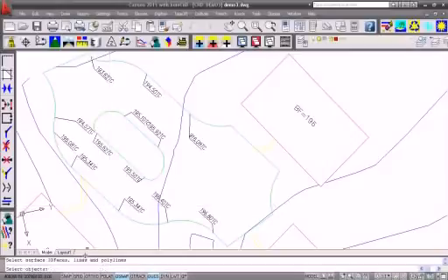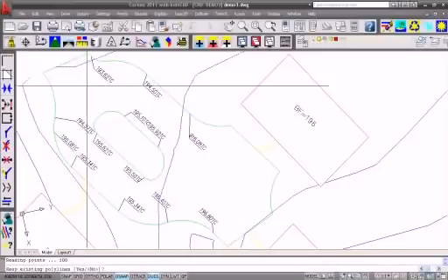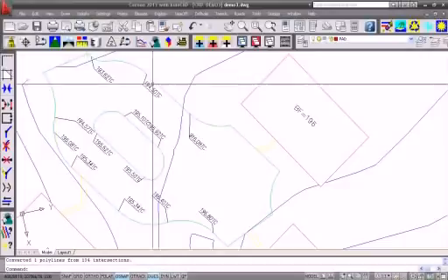And select the 3D faces, lines, or polylines to elevate it by. So I could type in all and select all the contours. I'm just going to click on the 3 that are close by. So I have 3 contour lines here selected. I'm going to hit enter. Keep existing polyline? I'm going to say no. And change the layer? No, I don't need to. And it says converted 1 polyline.